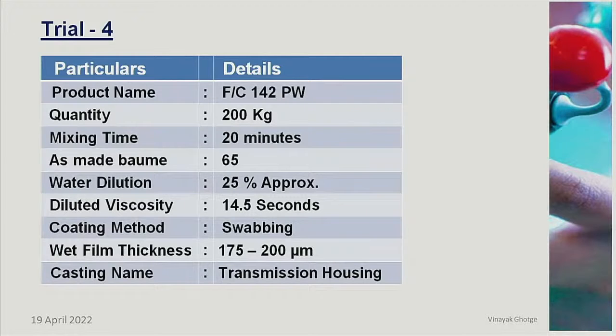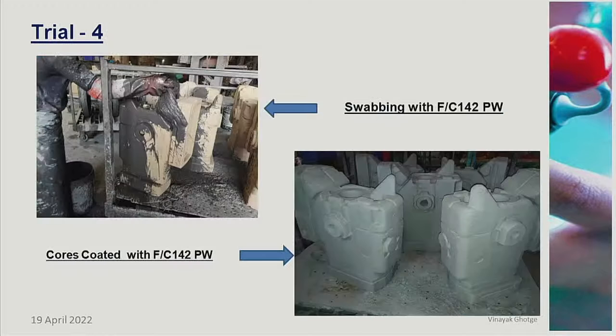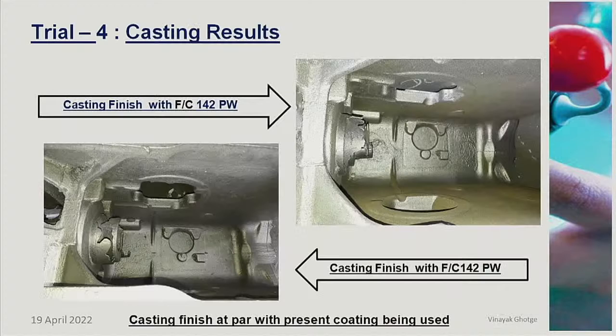One more trial of transmission housing only, but here the coating application is by swabbing. You can see the core being swabbed in the first photograph, and in the second photograph the coated cores, and you can see the casting finish inside. It's absolutely clean, no sand sticking.